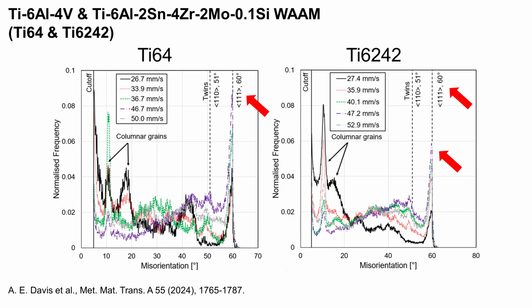For the 47 millimeter per second wire feed speed, the low misorientation peaks radically reduce and new peaks appear, most prominently at around 60 degrees. Phil and I had seen this misorientation peak before. It relates to twinning in the titanium beta phase. This was a truly bizarre discovery for us. Clearly, something else is going on that doesn't abide by conventional CET theory, but let's start there anyway.